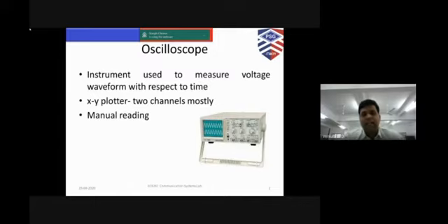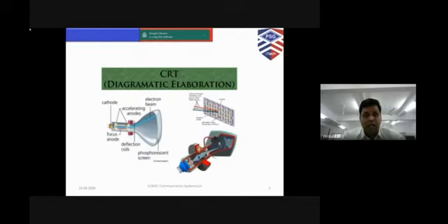And this is the exact usage of oscilloscope we have used in our laboratories. Okay, and this is the internal structure of a cathode ray oscilloscope, and we know that this cathode ray oscilloscope uses a CRT, that is cathode ray tube, where an electron beam will be deflected by the horizontal and vertical plates depending upon the input signal, and that will energize the fluorescent screen, where we will see an illumination of those parts depending upon the input signal, and where we can measure it.